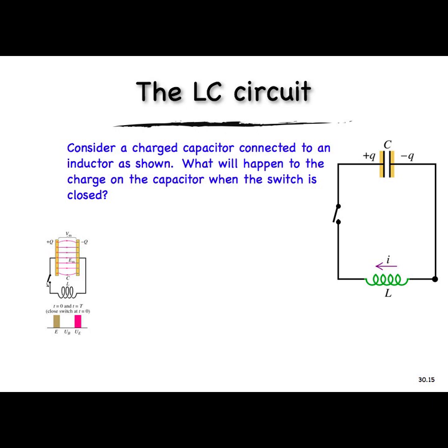And so when that switch is opened, that current wants to stop. It no longer can flow. I mean, opening the switch does stop the current. Current can't flow because there's an open circuit. But the inductance tries to keep the current flowing. You can think of it that way. And it generates an EMF that opposes that rapid change in current.